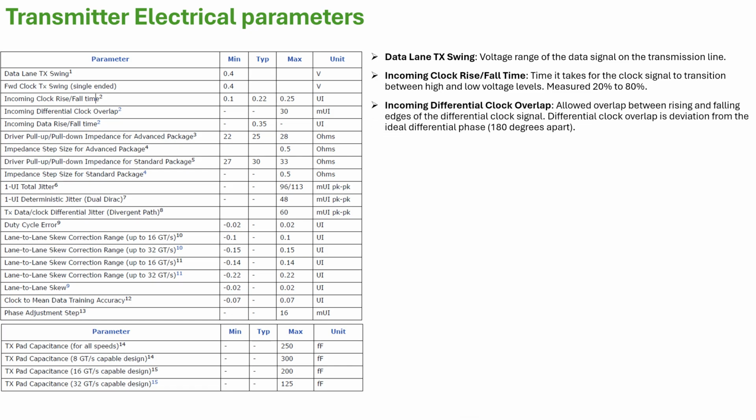The next one is the incoming differential clock overlap. It really matters because we talk about high speed. CML circuits, CML-based clock dividers, or master-slave flip-flops, you can imagine it. So we ignore the case when signals are simultaneously switching.